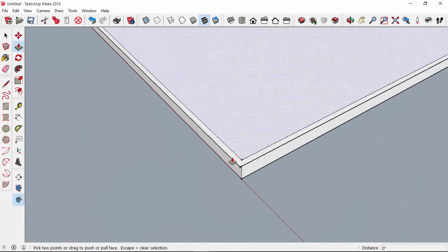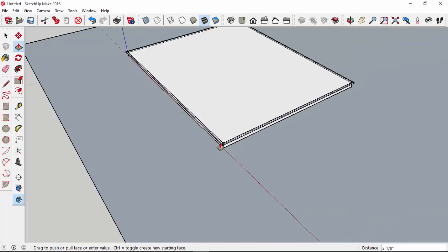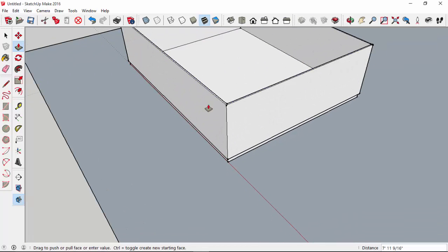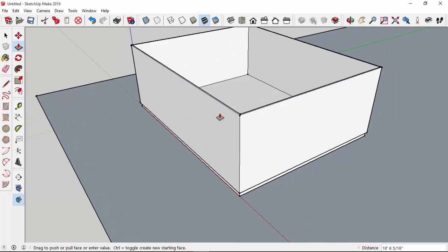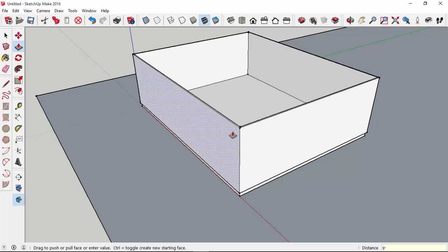And then we'll just do a simple cape for this model. And that's usually first floor only to the underside of the eaves on the front and the back. So that's usually 8 feet plus, we'll say, another foot for the depth of the floor joists of the first floor. So we'll say 9 feet. That's how much we'll pull that up.